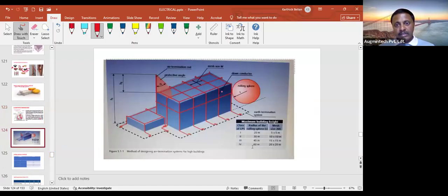So now you can see this, right? These are the levels of protection. We have four levels, class 1, class 2, class 3, and class 4, the level of lightning protection system we say. Class 1 is where we provide the highest protection, the best protection. Class 2 is the next. For normal residential buildings or general commercial buildings, we provide class 3 and 4 protection.